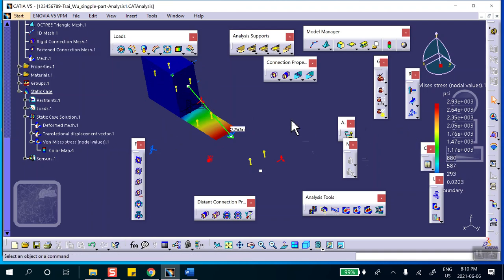There's very little stress in it, basically. With the heavy object, you just make this thing bend. Now, what I'm saying is that when you see red, doesn't mean that is the critical area, because remember, you're welding a beam to a plate and you're making the plate bend. Of course, there's going to be gigantic stress. There's no way you do something like that, because you know for sure that's going to cause a problem. This is going to be a weak point. But okay, good.